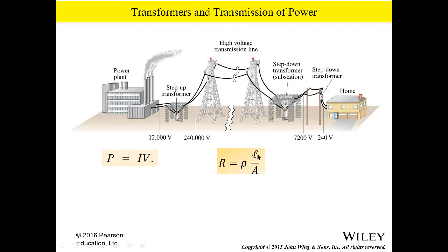And we then simply say, okay, I've chosen the best resistivity, and I now will be able to estimate, given that it is so many 100 miles, what is the total resistance of this wire? All right? And, well, that's just algebra. And the power now lost, the power that is lost through this transmission wire is I squared times R.